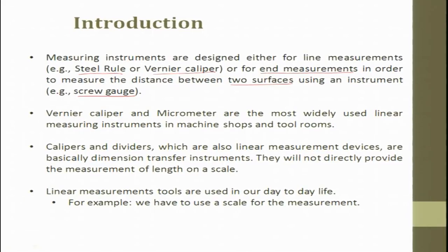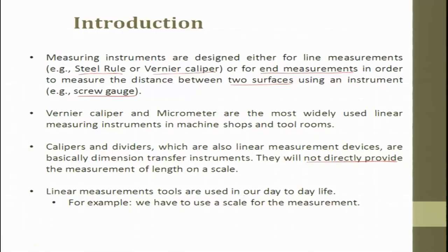They are basically dimension transfer instruments. They will not directly provide the measurement of length on a scale. It is just like a gauge: you push it inside, try it, note down the diameter, pull it out, take it to a scale, and measure it. The linear measurement tools used in our day-to-day life are many. For example, we use a scale for measurement and for drawing lines, and a mason always measures with a measuring tape. All these things are linear measurement.